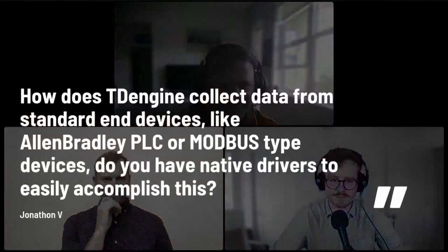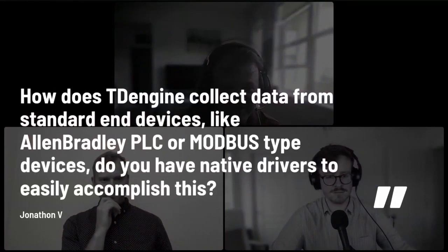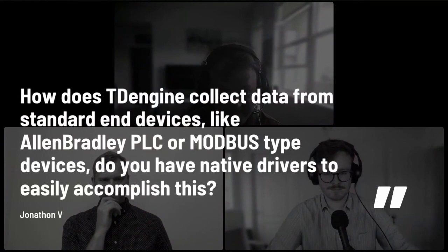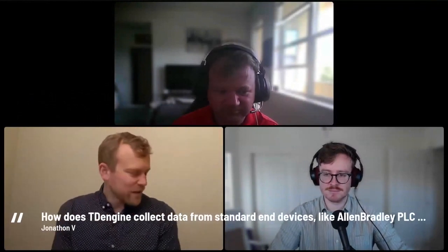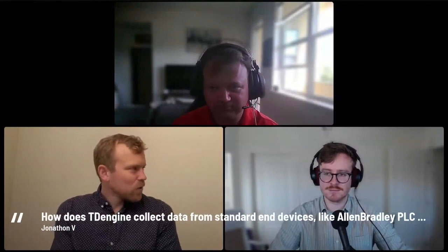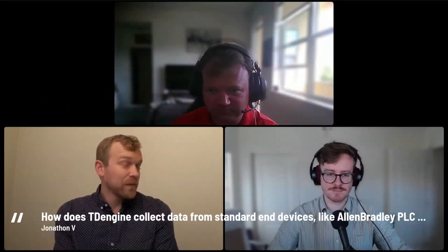The question is, how does TDengine collect data from standard end devices like Allen Bradley PLC or Modbus type devices? Do you have native drivers to accomplish this? Yeah, I'll answer that one. So right now we have a handful of native drivers that we've mentioned, some interfaces around MQTT and OPC, UA and DA.